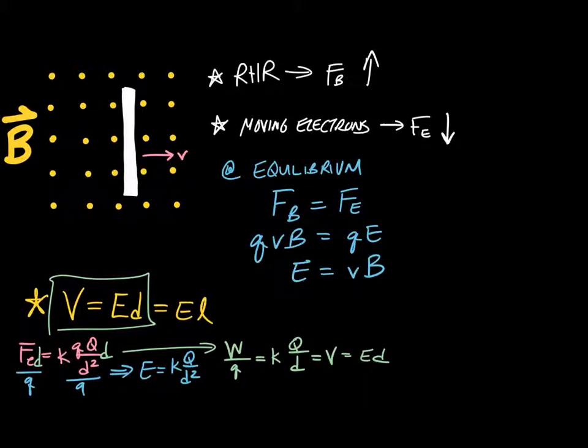And so, anyways, all of this boils down to the fact that my voltage equation in this case can work out to be, using this funny symbol for induced EMF, just the speed of the conductor, strength of the field, and the length of that conductor, because that voltage is set up over some path length.